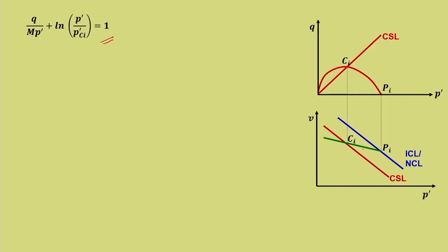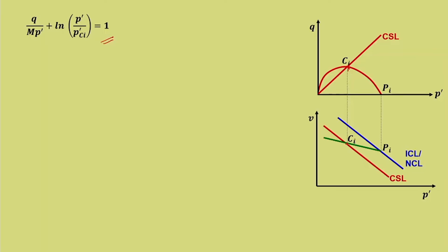In the last slide, we had not introduced this unloading line. Now, you can see that p' is here. This particular point Ci is nothing but the point of crossing where this unloading line is crossing the critical state line. I would not say that it is touching, it is only notional in this particular plot, v-p'. It is the point where it is crossing. So, this particular point corresponds to Ci.